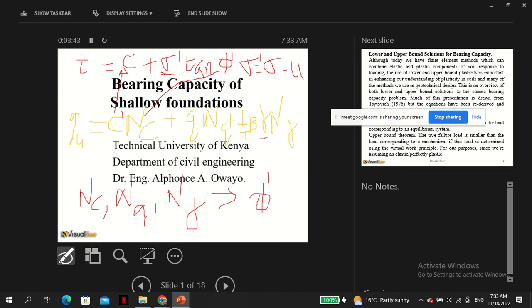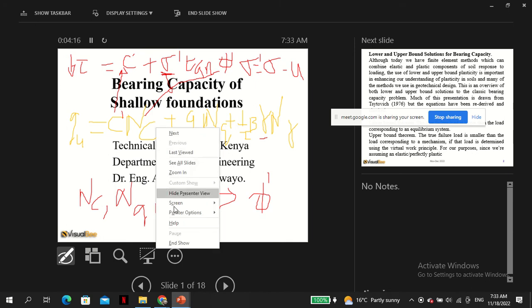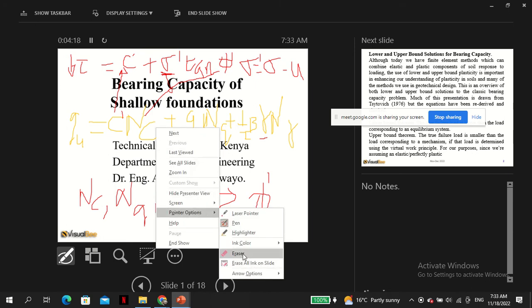So if someone tasks you to explain why probably at the onset of rain a lot of buildings collapse, you can see it's tying together that the excess water pressure reduces the effective stress, and if this value in the formula reduces, then the strength of the soil, which is governed by this formula, goes down. So this is the key idea.